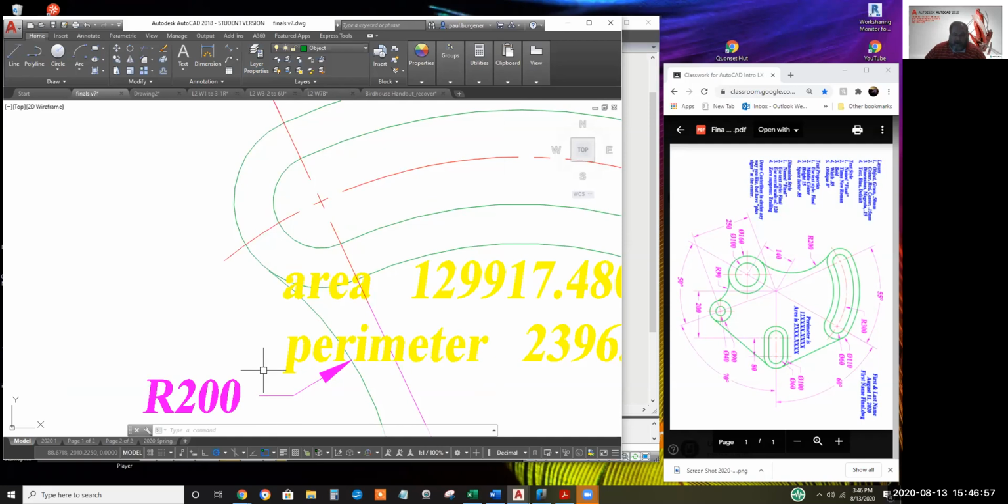Before we go there, let me type LT scale or LTS enter, and it's simply 1, which I think would probably be wise. If we all agree to keep LT scale 1, it'll be easy to share drawings with other people and copy paste items from one drawing to another.